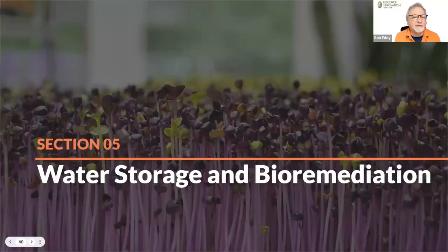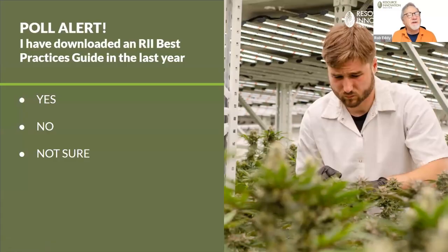Okay, I'm going to talk a little bit, just one slide, on storage, just a couple of points about storage, and then we'll talk about bioremediation, which will be fun. Bioremediation wouldn't get you to zero liquid discharge, well, I'll hedge on that a little bit, because it's usually done outdoors, so you're letting the liquid get outdoors. So strictly defined, you're not zero liquid. But it is another way to treat water that's left the facility so that it doesn't go into the sanitary sewer or a local body of water.